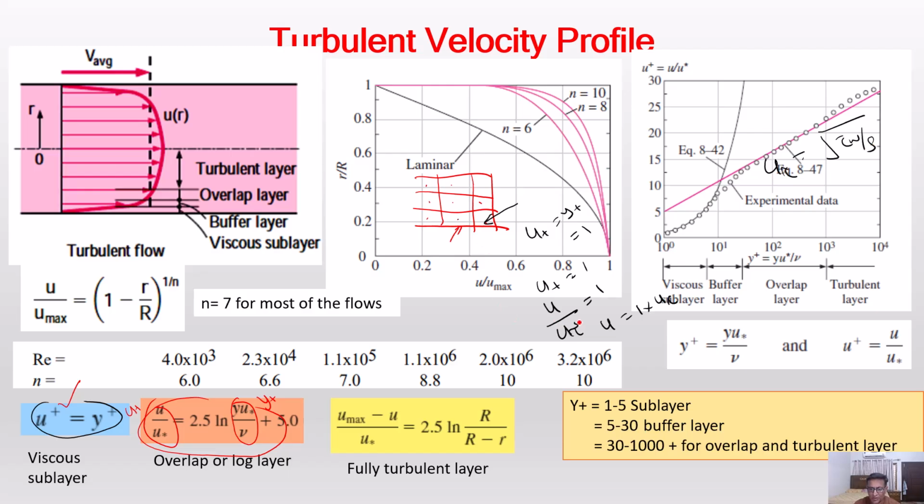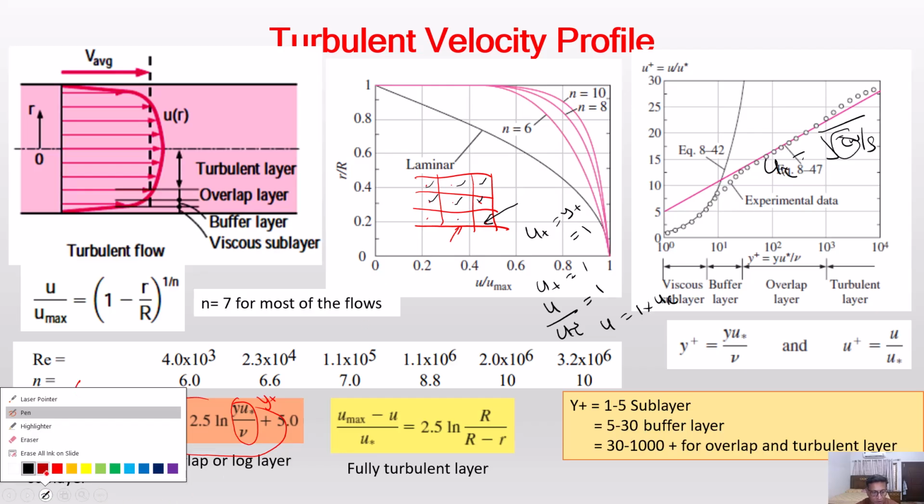Once you find this value, you can find the velocity from there, and tau wall comes from the wall conditions. So we can now put the velocity at these different locations, and these velocities may be different because y plus may be different, and maybe the friction velocity is different. With a different friction velocity, y plus will be different, and so u is different. Then once we provide the properties here, these points will be solved numerically by the solver. So that's why this is a very important thing to do.